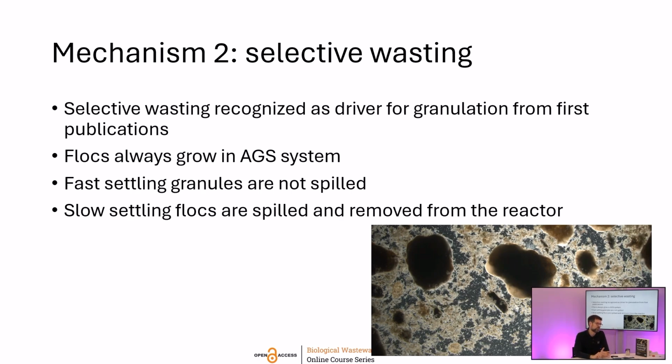At the same time, those flocs also play a role in the conversion process. For example, in the nitrification process, they really play a role there. So while in the lab scale we can run completely on granules only, in full scale you will see that the flocs also play an important role. But in the end, the granules are important to have simultaneous nitrification and denitrification, and really make your total volume smaller. So you have to keep throwing away those flocs, because if you stop doing that, the granules will disappear in the end.